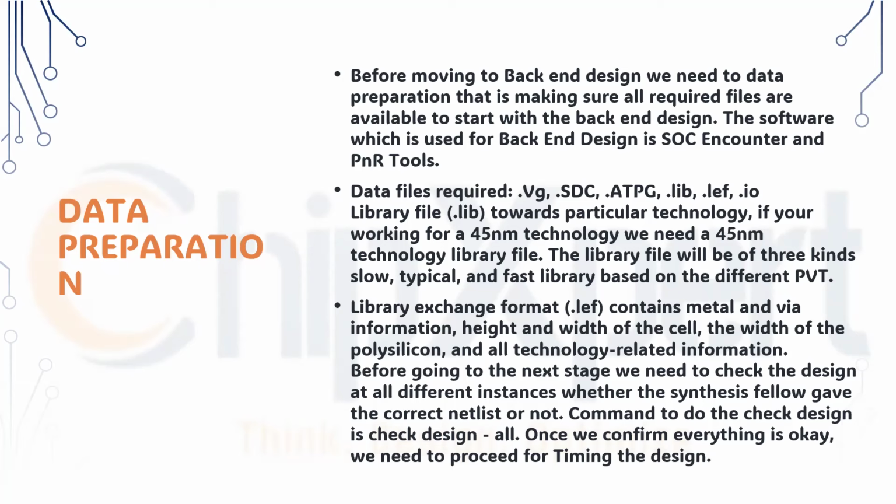We require a Verilog file. We require a constraint file, that is the SDC. We have a scan file, the ATPG file, which is a scan file. Libs are the timing libraries for each cell. There is a characterization, right? That is like the features or specifications of each cell, and those are the libraries. Then the layout exchange format, that is the LEF, along with input-output files and library files.